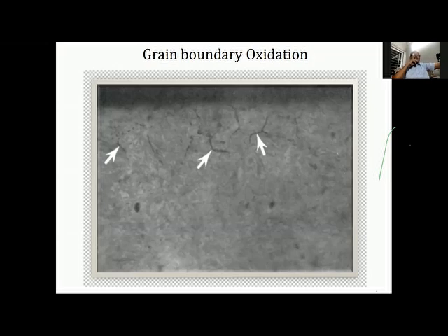Now, in most of the carburizing furnaces, the atmosphere, which is endo-based, is generated by partial combustion or cracking of a hydrocarbon like LPG mixed with air, and so there is always some amount of oxygen present, some ppm of oxygen.